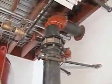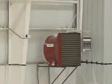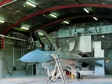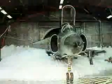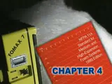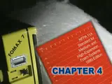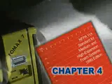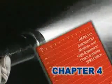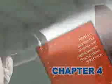Successful tests like these, coupled with lower installation costs, no containment requirements, and the use of inside air can explain why the United States Air Force recommends high-expansion foam systems for military hangar protection. NFPA 11A Chapter 4 provides guidelines when medium and high-expansion foams are applied manually using a portable foam generator, or special air aspirating nozzles commonly connected to the foam solution supply.